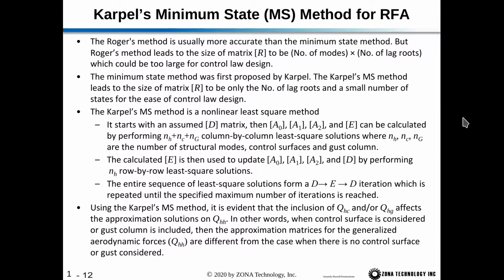Okay, so now we'll talk about Karpel's minimum state method for the RFA, which is the original minimum state method that we implemented. Rogers' method is usually more accurate than the minimum state method, but Rogers' method leads to the size of matrix R being number of modes times number of lag roots, as we said, which could be too large for control law design.